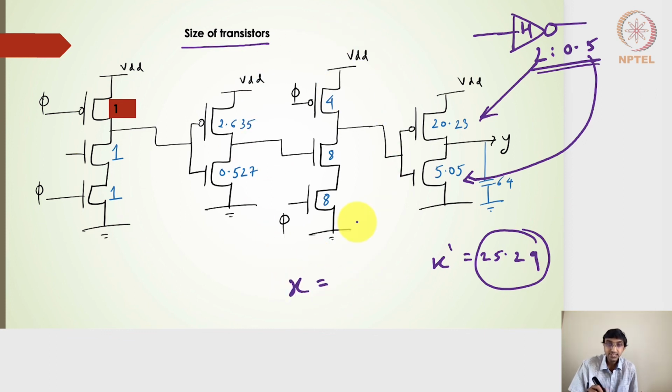And similarly, the X value for the dynamic inverter, which is the gate size of the dynamic inverter, was 8. So 8 will be put in here where the input is connected. And for the foot transistor, it should be similar to that. And then for the PMOS side, we will take half of it, right? And this one also, whatever value we obtain for Y dash, we will do 2.5 parts. 0.5 parts will go here on the NMOS side, and then two parts will go into the PMOS side. Lastly, the gate size is anyway 1 here. So we will have 1, 1.